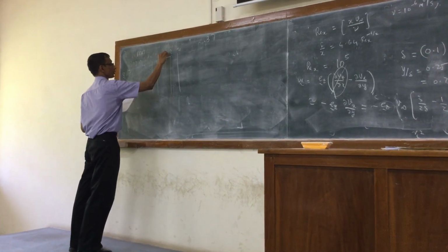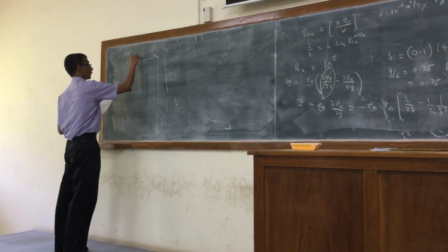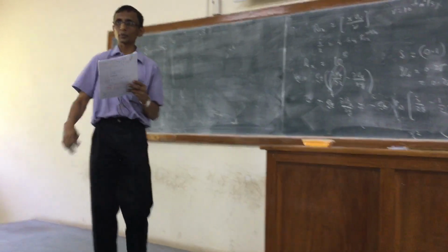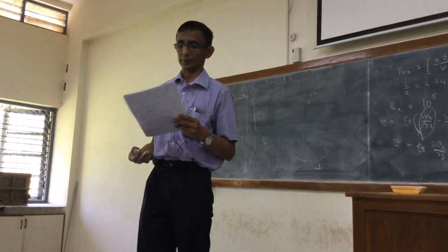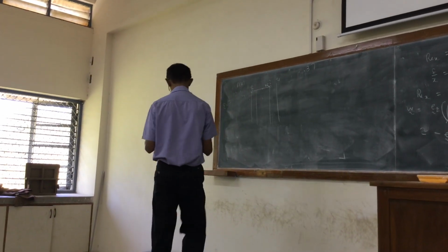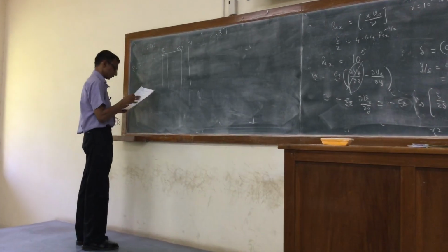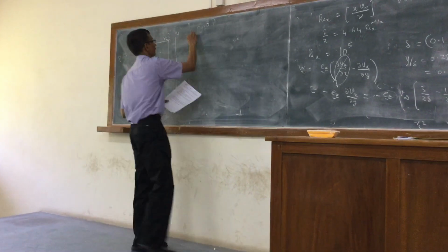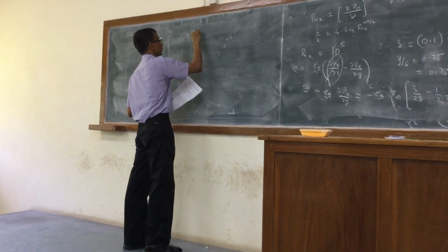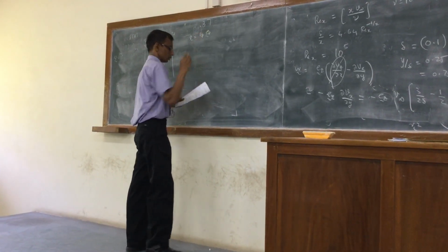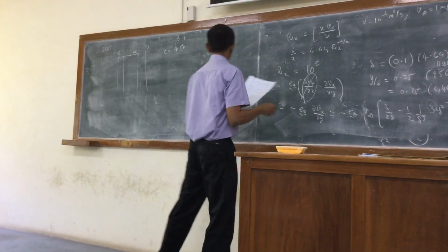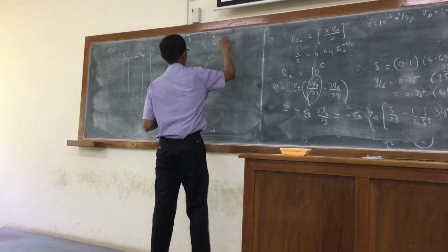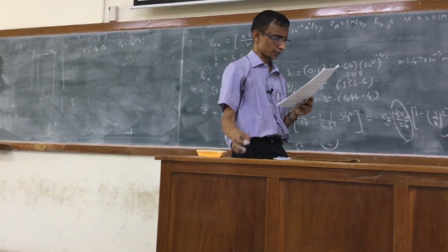One at radius kappa times R, another at R, and you are already given that it is rotated, and on top of it, the fluid is also being heated because of the difference in temperatures between the inner and the outer cylinder. So there is a temperature gradient also. Again, if you assume constant viscosity, we have already solved this problem, V in cylindrical coordinates, and we have made so many approximations that we find it is a function only of r. So we have solved it.